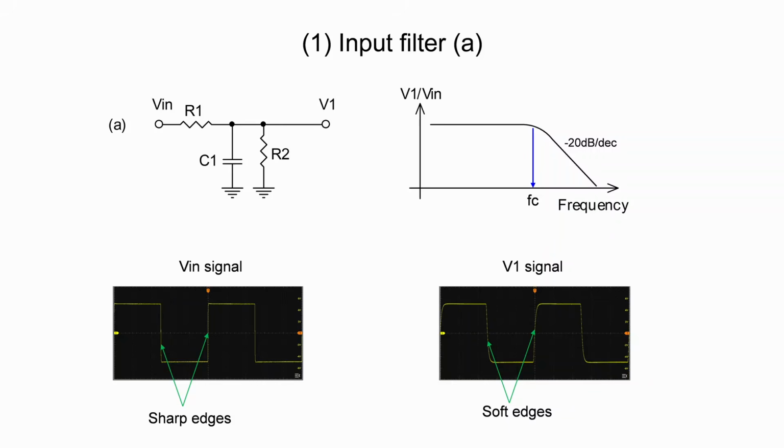In the real world, it could be a fast transient signal with large amplitude getting into the power amplifier. The low-pass filter softening effect is useful as it helps minimize the chance of overloading the input stage of the power amplifier. However, the input filter alone will not completely avoid this from happening, but the input stage also needs to reduce the voltage gain at the same time. We will come to this when we discuss the input stage.